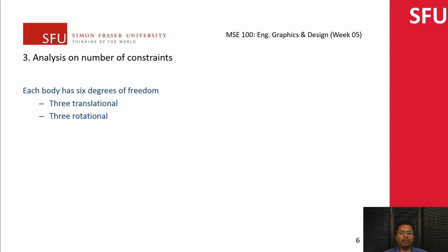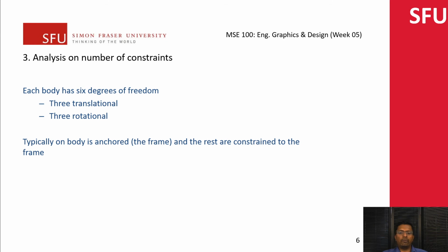So that allows you to calculate how many mates you would need. Let's note that down. So the first object gets fixed to the frame. For the rest of it, we physically think about moving the object, and then we see how many constraints we would need. So here things get a little bit more dicey. There isn't really an easy one-to-one correspondence for the mates because we're in 3D.